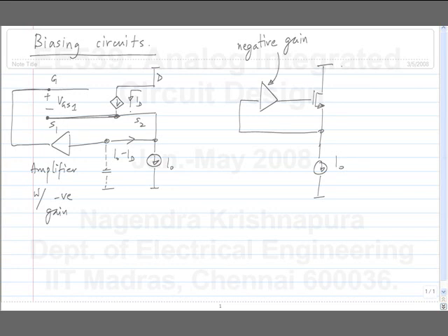If you recall the third circuit, what we did was, we had this and a comparison of current, and we connected this to a fixed potential and connected the sources together. So this actually has feedback both to the source and to the gate. It has feedback to the source because of the implicit connection between the input and output side. It has feedback to the gate through the amplifier. Is it okay? We will see practical realizations of this soon. So it turns out that, as before, if you want negative gains, you can use a common source amplifier. We will look at it shortly.